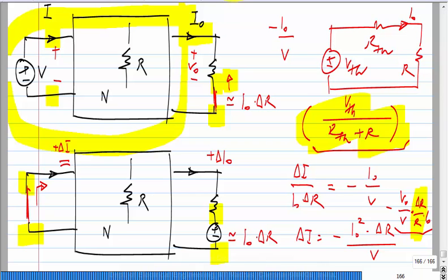Okay. So, if let us say 1 kilo ohm resistor changes to 1.1 kilo ohms, you will get some solution, and you evaluate it using this approach, you will get a slightly different one, because the delta is 100 ohms, it is 10%. The delta I times delta R term may not be negligible. But as the change becomes very small, the 1K resistor becomes 1.001 kilo ohms, that is, it changes by 1 ohm, it becomes closer to the actual one. So, it is somewhat like finding the derivative, that is all. Okay. The other ways to derive this also, just think about it and see.